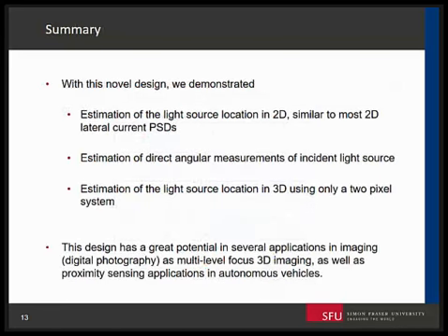Now, in summary, using all this data, we'd like to fortify our proof of concept regarding how differential photocurrent measurements in our pixels would allow us to estimate not only the angle of incidence of a radiation source, but also other additional information such as the azimuth and the distance to the plane of detectors. The reason we think this is a very promising technology is because being able to tell which source of radiation is approaching your plane of detectors, and at what angle, is going to have an enormous impact on industries such as robotics.